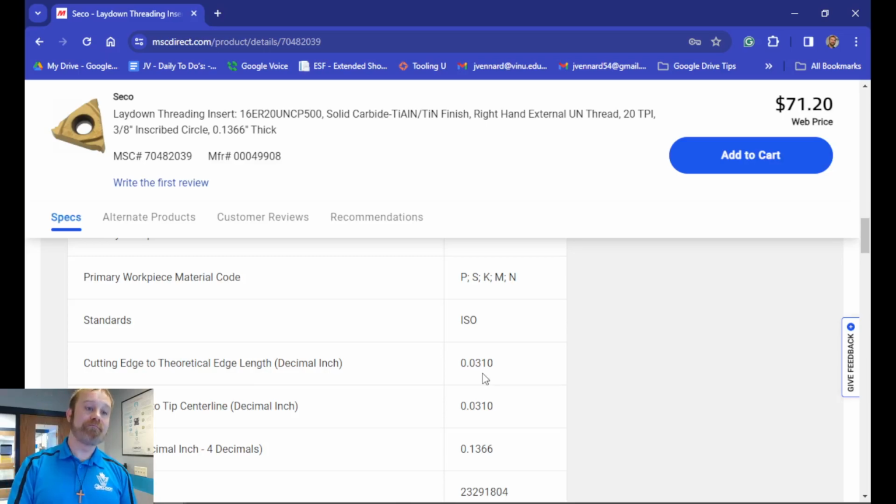I've had people, believe it or not, I think it was on that lightsaber project when Austin was making it, fighting threads, couldn't get the threads. Came to me, he's like, I don't know what's wrong. I looked at his program, everything's right. I don't know what's wrong either. Everything looks good here, and I look in the machine, I look at it again, and somehow he had gotten his hands on a left-handed boring bar threading insert.